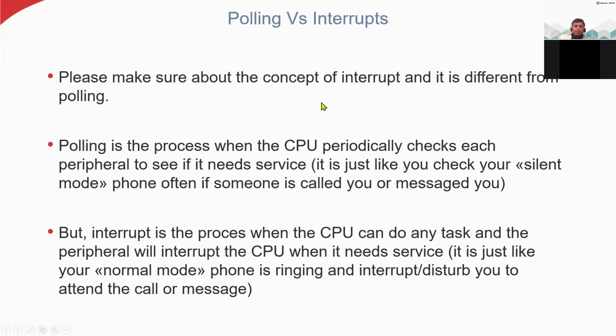So the polling is not really disturbing the CPU operation. It's not interrupting the CPU operation. Every few seconds, the CPU is coming and checking if there is any service needed or not. It's just like your mobile phone. If you keep your mobile phone in silent mode, for example during the lecture, but still maybe you are expecting some important message or call from your friend.